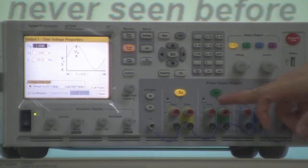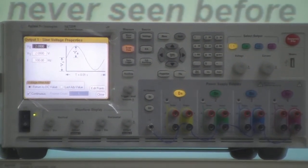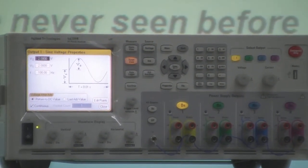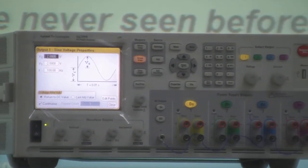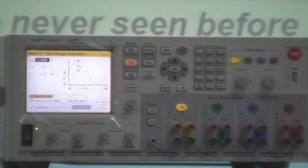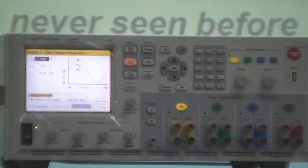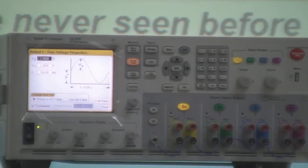So let's say you have two sine waves, one in channel 1, one in channel 2. Same differential. Oh, differential. Yeah, sine wave channel 1 with a different phase in channel 2. Oh, okay, a different phase. Yeah, it's a time delay. So if you know the period, then you know what half the period is, a quarter of the period is. Then you can program that phase difference as the time delay. Then it will sync the phase, invert it, or just set it off by a different timing.